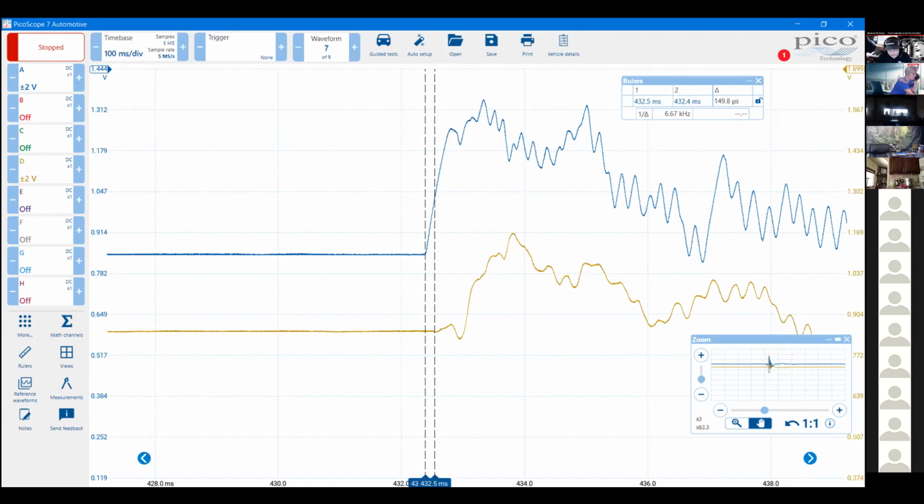Most of you listening to me out there have had a car that has a suspension squeak or a clunk. You've got a squeak, you've got a clunk, you've got a noise. You realize noises do not travel well through the air. Oh, noises travel through the air, but not real good. Air doesn't propagate a noise very well. However, noise travels very well through certain materials: aluminum, steel, hollow tubes. Different materials transfer sound at a different rate of speed. A noise starts here, poof, winds up over here.